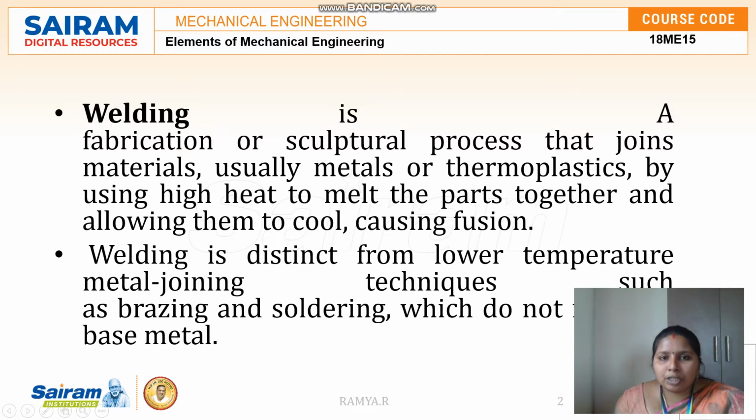Welding is a fabrication or sculptural process that joins materials, usually metals or thermoplastics, by using high heat to melt the parts together and allowing them to cool, causing fusion. Welding is distinct from lower temperature metal joining techniques such as soldering and brazing, which do not melt the base metal, but in the case of welding it melts the base metal to create the joint between the two workpieces. So either two similar or dissimilar metals can be joined with the help of a welding process.